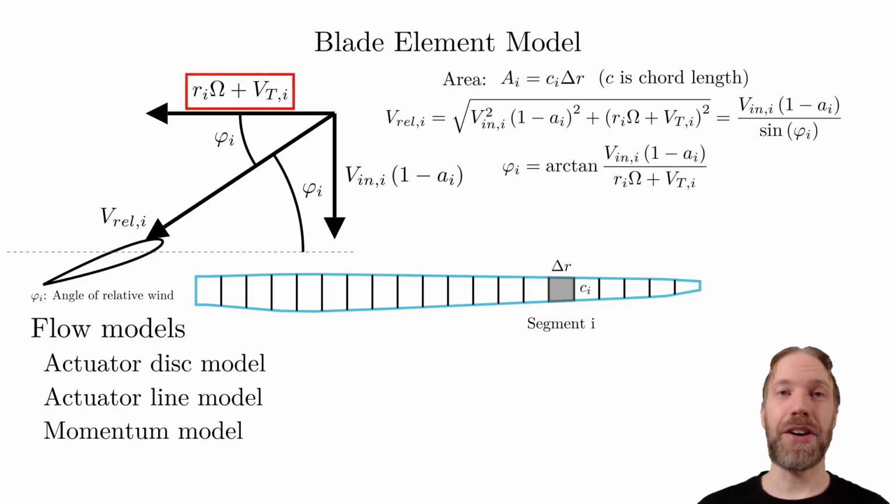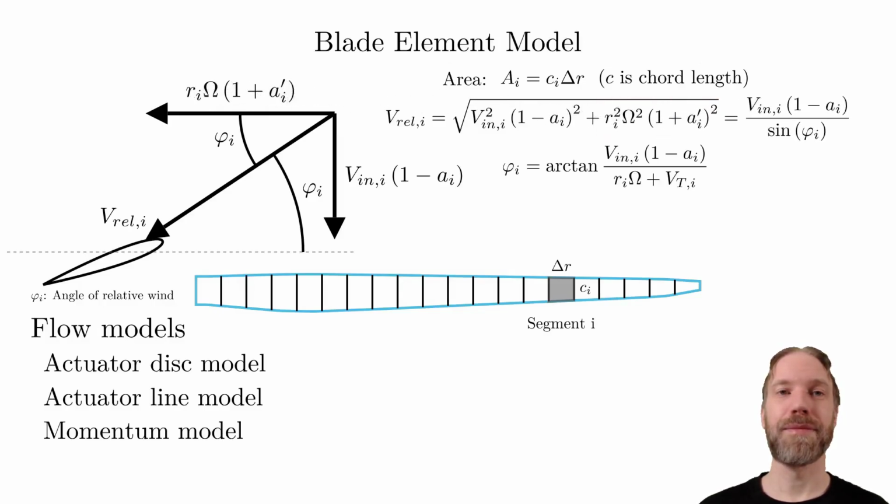In the tangential direction, we had the angular induction factor A'. Update the flow velocity using the angular induction factor. And update the angle of relative wind.